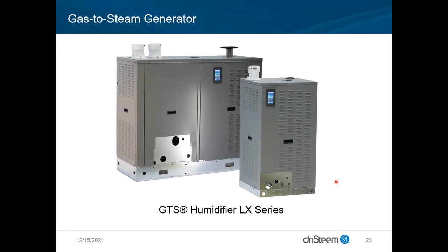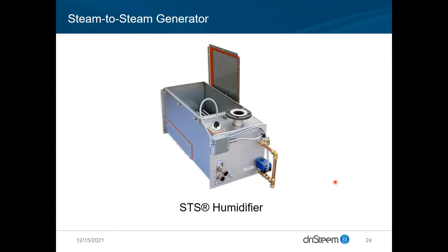We talked quickly about gas humidifiers. There's a number of reasons, again, besides your energy efficiency. They're very easy to install. You've got condensing humidifier options and sealed combustion. Outdoor enclosures are available as well. Typically, these are put on roofs a lot of the time for ease of installation, and a very tight tolerance system as well. But again, gas units, larger capacities, less operating cost.